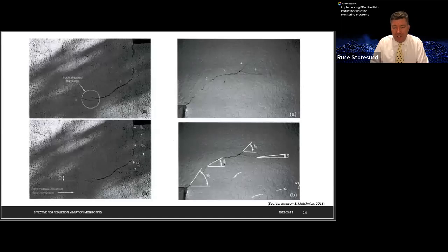So at the end of the day, much of the litigation associated with construction-induced ground vibrations focuses on either the appearance of cracks or the enlargement and reactivation of existing cracks. Doing a crack-by-crack analysis can be very time-intensive, usually entails a high degree of uncertainty, and in my experience with the litigation world, just results in experts arguing and disagreeing with each other.